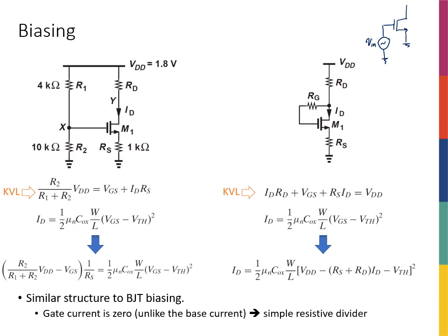If I want an amplifier out of this, I'm not going to get a good one at least, right? The reason is that for this transistor to work like an amplifier, I need to make sure that the transistor is first on, right? And I need to make sure that it is in the saturation region, similar to the BJT transistors, where we needed to make sure that the transistor is on and in the linear region before actually being able to amplify.